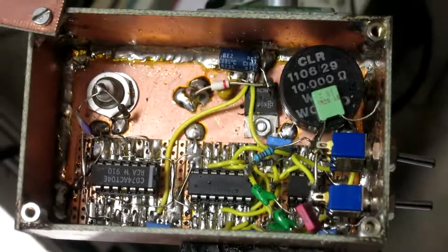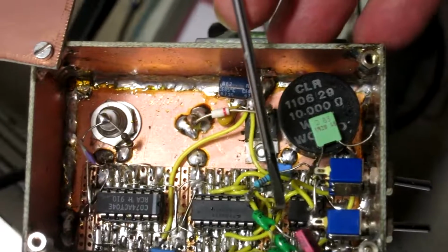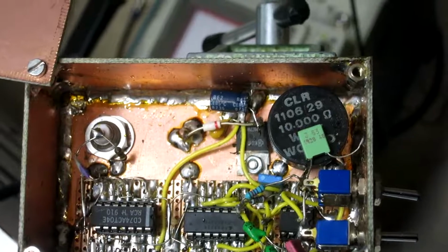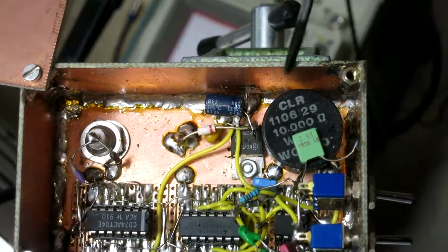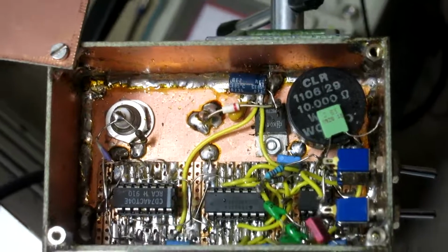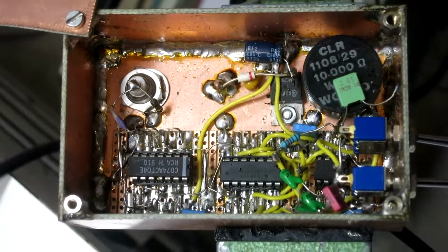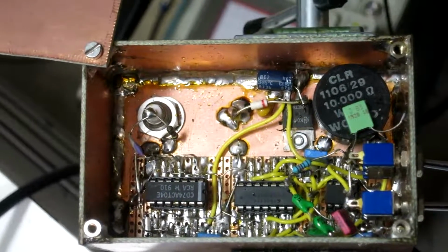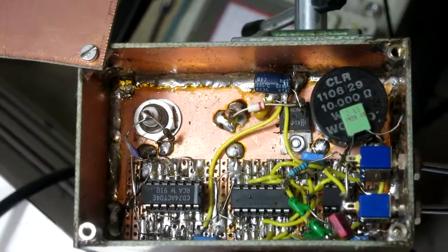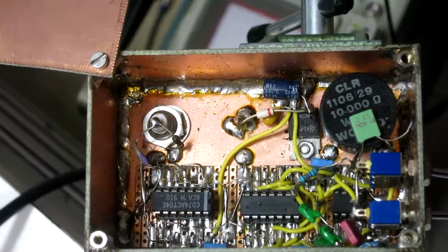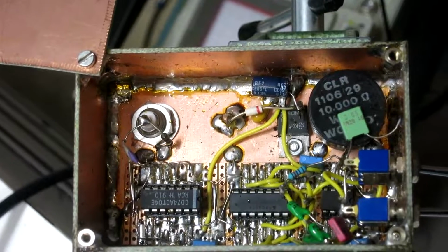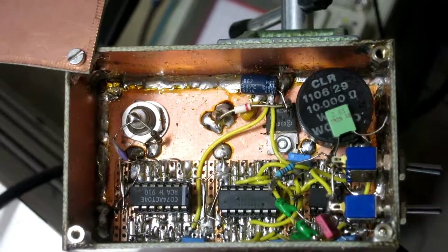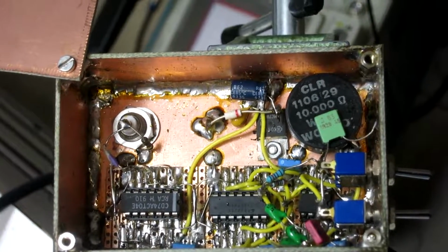This is a proper pulse generator. It has a 555 here that oscillates at a frequency that can be set by the switches here and the potentiometer. It's just a standard circuitry for the 555. It's followed by a 74 AC 74 that divides the frequency by 2, and by doing that the pulse length is ensured to be the same for positive and negative halves of the square wave.